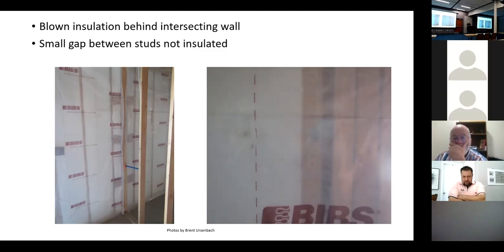So are you talking about the insulation on the outside, removing the vapor barrier? So that stupid people like me, in my house, I would not put in the vapor barrier, spend the money on it, and destroy my house. Yeah. We're seeing more problems from vapor barriers than they've solved. We really are, historically, all over the place. And we're seeing lots and lots of water damage.